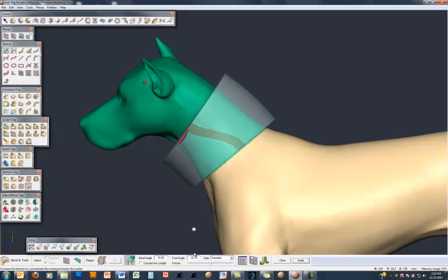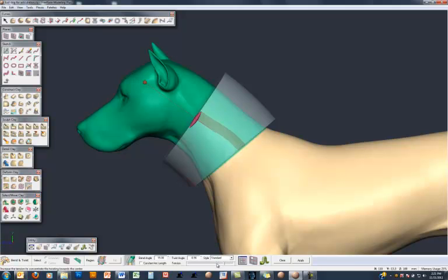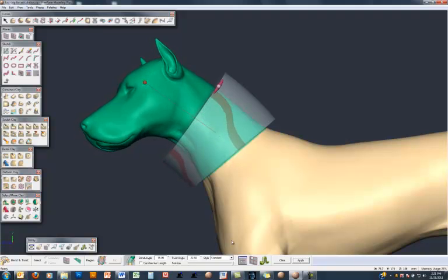Now the tension of the twist, this is how smooth the in and out of that deformed area happens. So you can see how right on the border of the widget we have these bars which help us visualize how the twist is going to happen. I could take that all the way to the left, and then you see how the twist is much sharper. There is no smooth transition zone. Or if I take it all the way to the right, you can see how we have a much smoother transition in and out of that bend area.